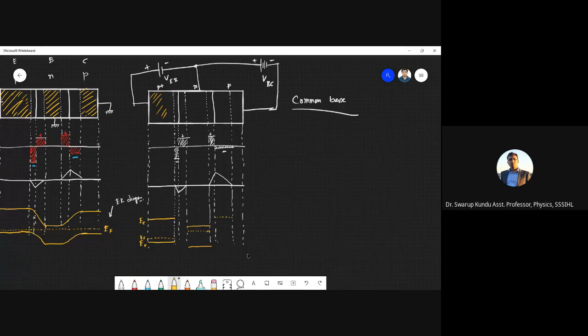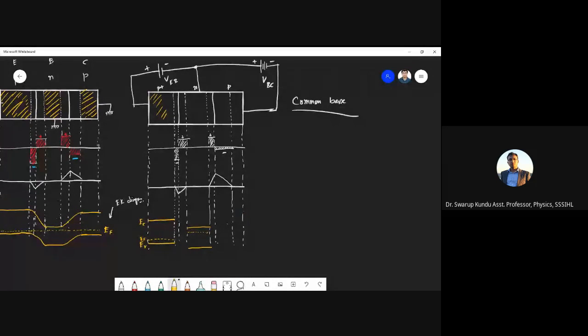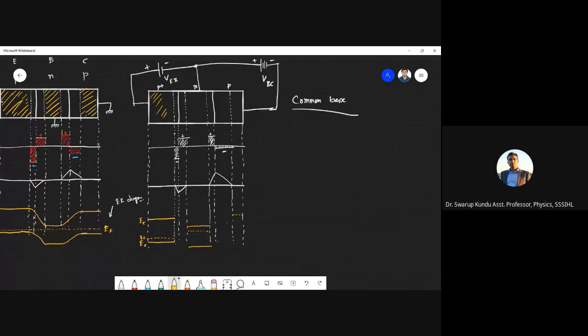So now let's draw the P side. So again, this side is lightly doped. Oh, not here, sorry. So this is the depletion region. Okay, sorry, I was drawing wrong. This region is still the depletion region. So the Fermi level, we draw it only in the neutral region, right? In the depletion region the bands basically bend according to the electric field. So this is the Fermi level, and this is P type.